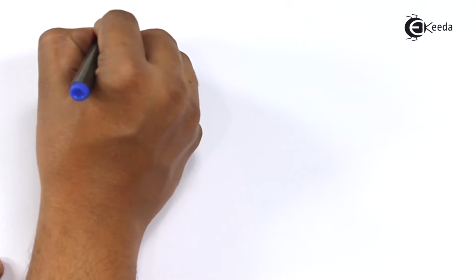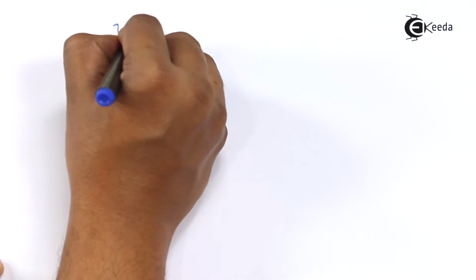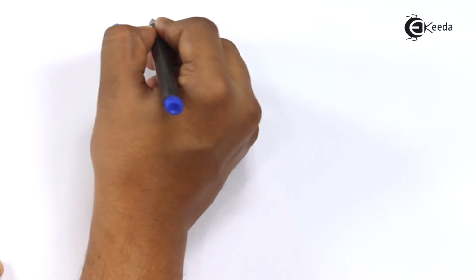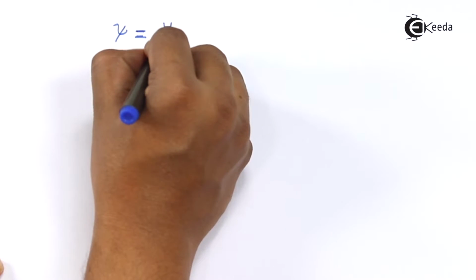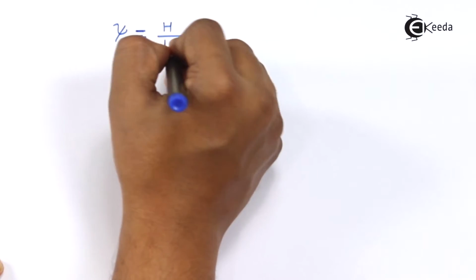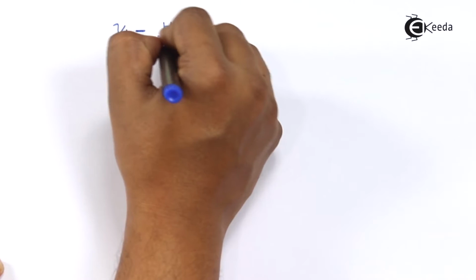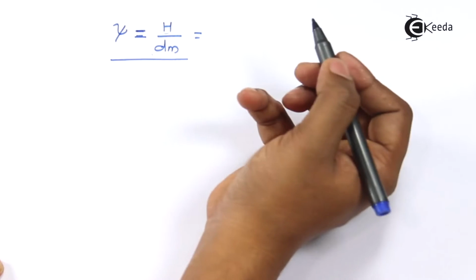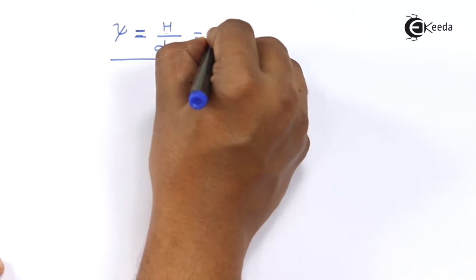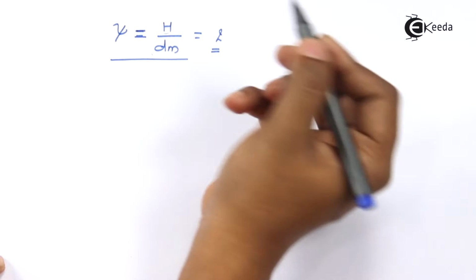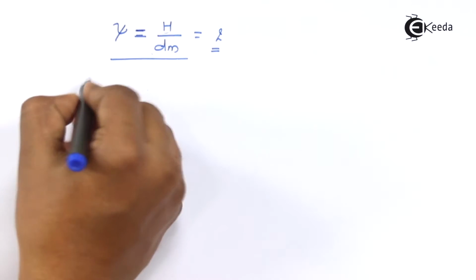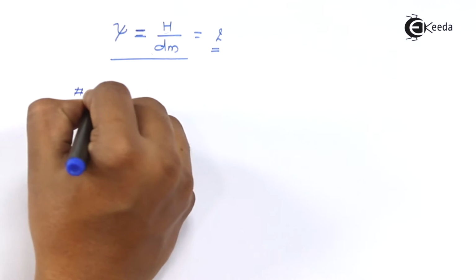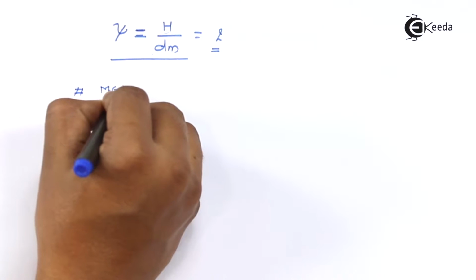And of course, the angle psi which is associated with screws, let's say it is h by d mean. We'll be dealing with this component separately, but it's a standard empirical relation, so let us use it, and the desired value is 2 for us. Now let us calculate the mean diameter, which is dm. That's the mean diameter calculation.